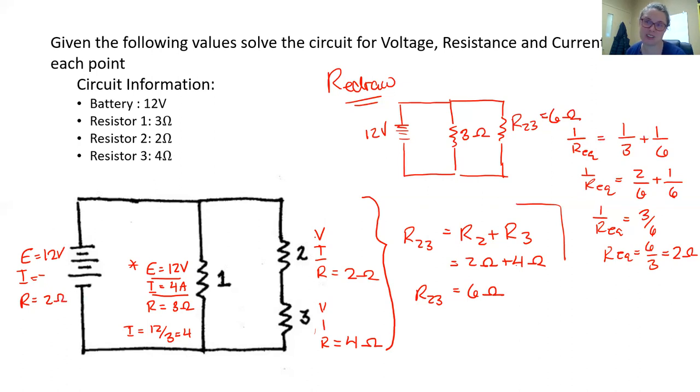Can you use Ohm's law yet? We can. We can use Ohm's law here. So current is going to be equal to 12 over 2, which gives me 6 amps. So 6 amps leaves the battery. If 4 amps goes down this section, we know 4 amps has to go through this section as well. So, oops, not 4 amps, the remaining 2. So we get 4 amps goes this way and 2 amps goes that way. It adds up to be a total of 6.